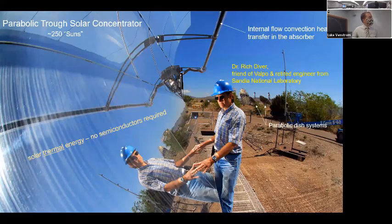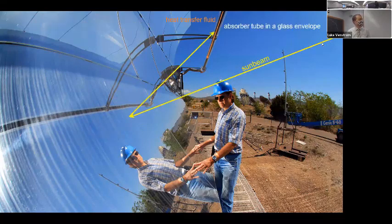So how these parabolic trough concentrators work: you have sunlight that comes in and it's reflected down to an absorber, and in that absorber you have a heat transfer fluid that flows. So we're seeing internal flow convection heat transfer inside of the absorber. So this is the idea. Sunbeam comes in, it's reflected by the parabola mirror onto the absorber, and the absorber is actually inside of a glass envelope. Why would that be?